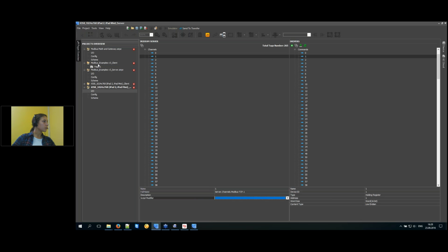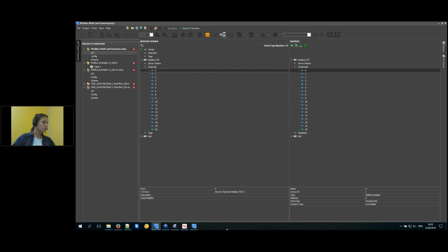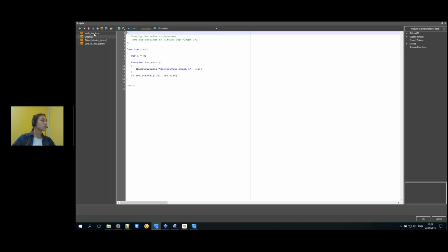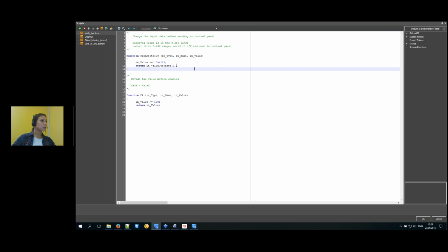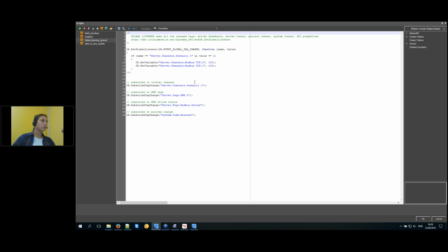I'll show you a ready example. Here you can see the modifying function related with the feedback of Modbus driver. Inside of this modifying function, you can see some list of actions. It could be mass dividing or multiplying. It could be gatewaying from Modbus to another automation system.